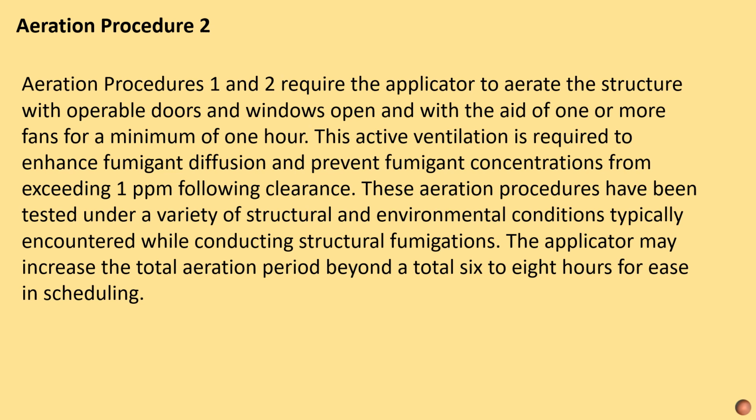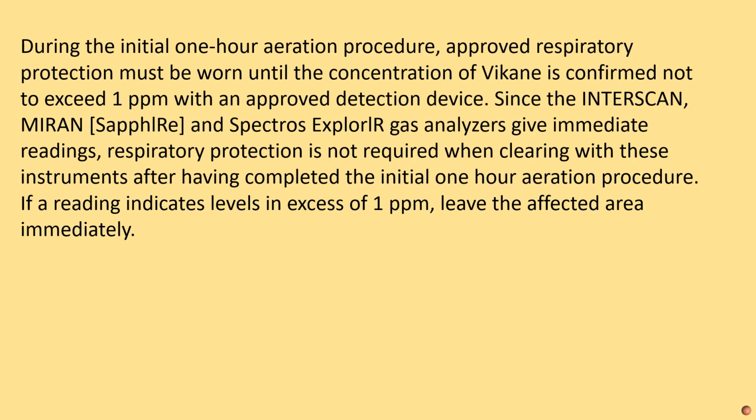During the initial 1-hour aeration procedure, approved respiratory protection must be worn until the concentration of Vikane is confirmed not to exceed 1 part per million with an approved detection device. Since the Interscan, Myron, Safari, and Spectros Explorer gas analyzers give immediate readings, respiratory protection is not required when clearing with these instruments after having completed the initial 1-hour aeration procedure. If a reading indicates levels in excess of 1 part per million, leave the affected area immediately.